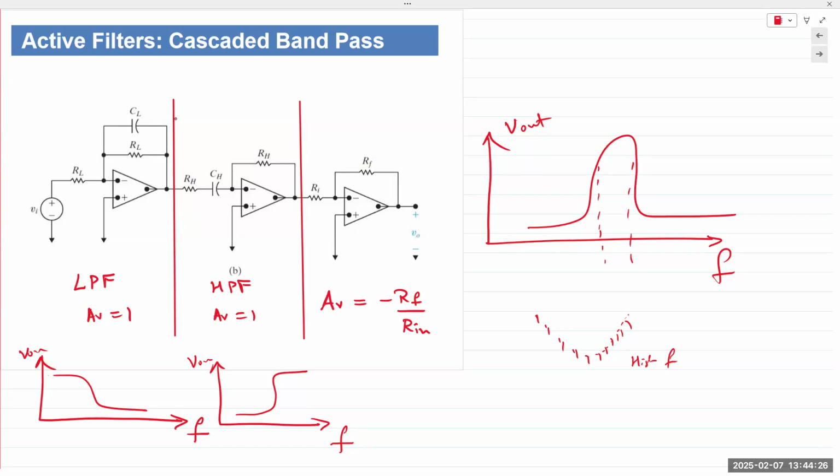How are they doing that? Well, filtering is one of the options. You have a filter at the front end that only allows the Verizon signal to come in, and those signals are amplified, while the other signals are blocked. An AT&T phone works the same way. Locking down a phone on a network can take many different forms, but the device by itself has a filter in the front end, so it only allows certain frequencies to come through, and everything else is blocked.